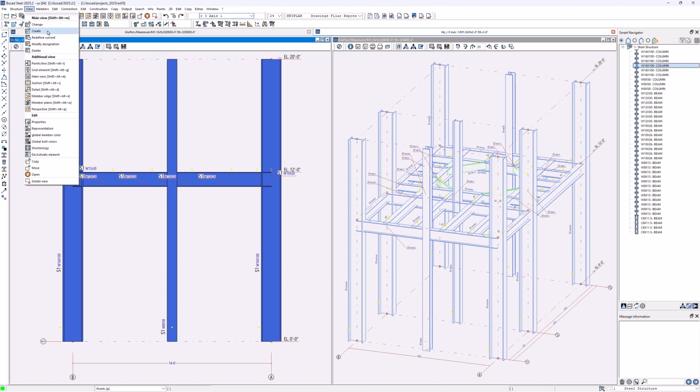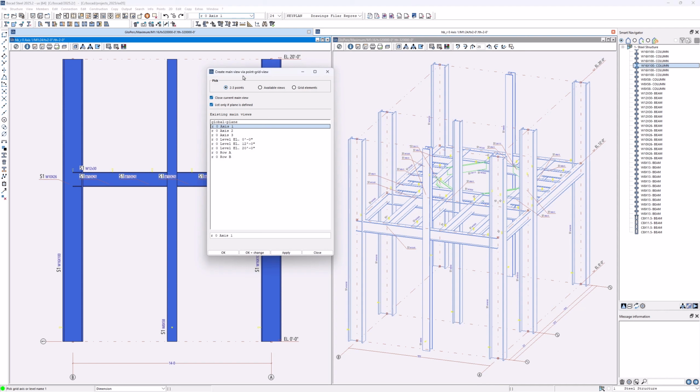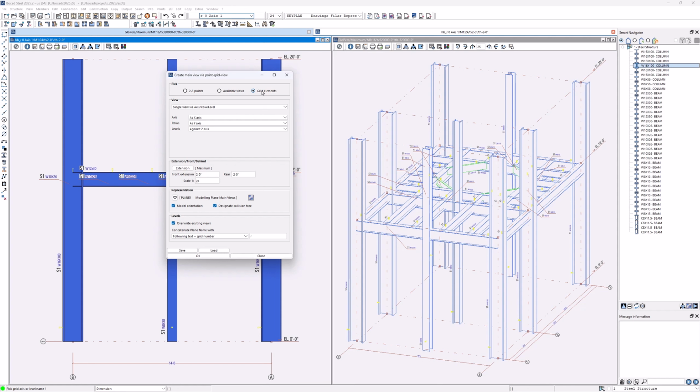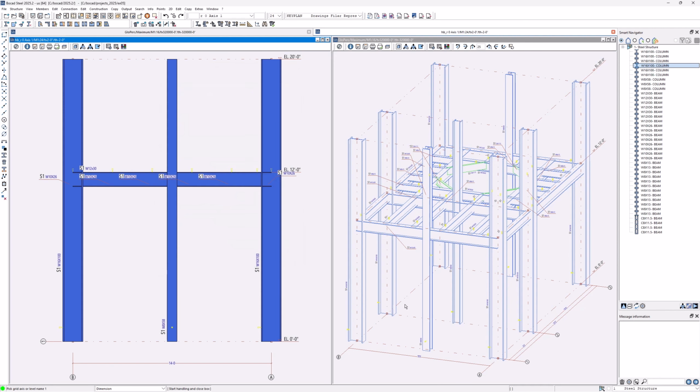It's also possible to create a new view. And that can be done in various ways. It can be done simply by clicking a grid element, like we just did from the little pull-down menu. So grid element, we follow the X, Y, and Z axis, or we go against it. The views also have a depth, and OK, just double click an axis, row, or elevation. And it says, by the way, the old view was deleted, a new one is created.